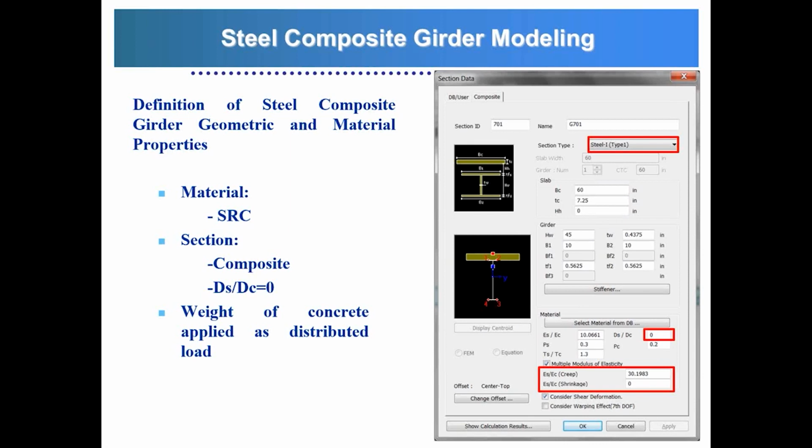Now to consider the weight of the deck, what we're doing is applying the weight of the concrete deck as a distributed load over the floor beams. And also, MIDAS allows you here to consider the effects of creep and shrinkage based on the modular ratio.